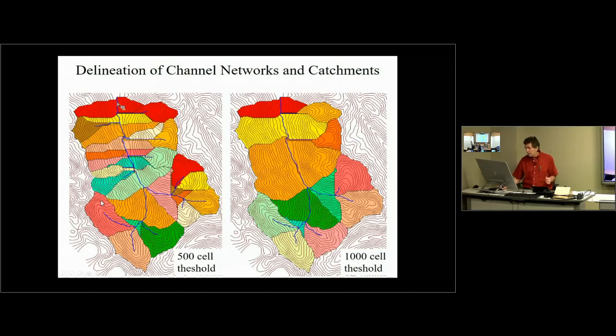Well, what I'm posing here is the idea that in this little bit here, we've got a small catchment, and if we've mapped this as a stream, we're going to represent this as overland flow up until it hits the stream, and then in-channel flow. Whereas if you've got a coarser threshold, you've got overland flow all the way to the stream.